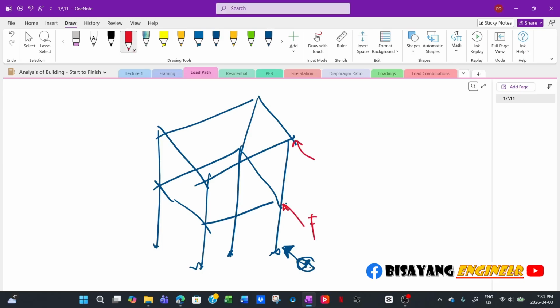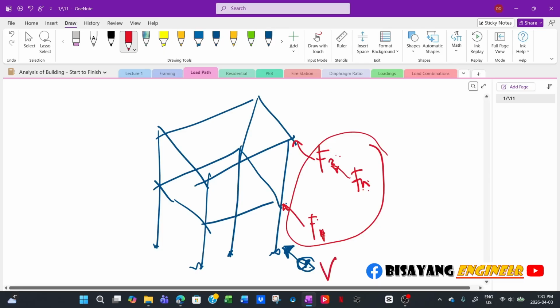So you have F1 and then F2. There's a calculation on that, and then you could probably have F_n. It depends. But the total, all of this, F_n, F2, F1, you add these together, then that is equal to your base shear. Now, before you analyze this one, you transfer this load here. You also analyze, how is it transferred?